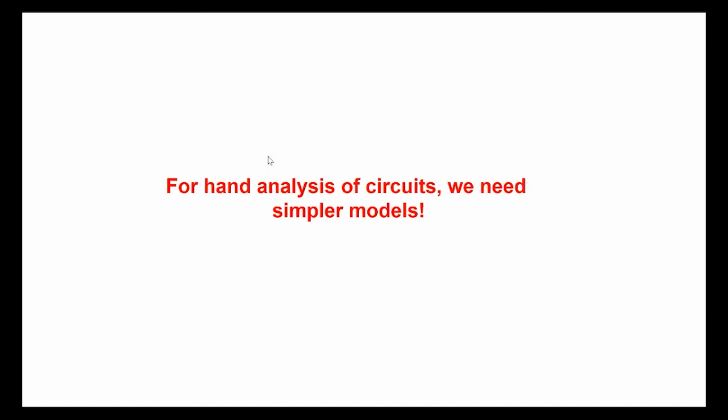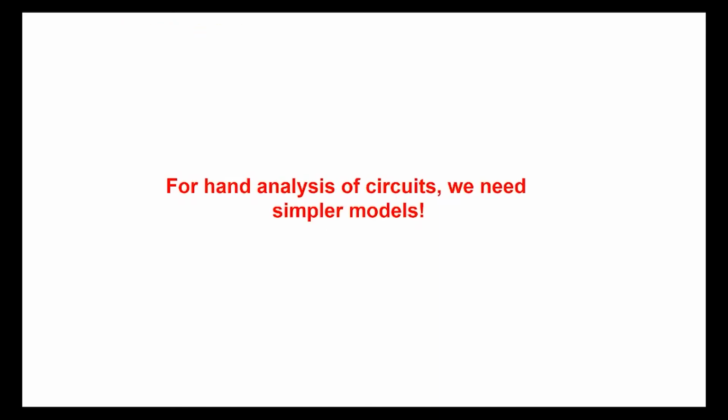All right, but both of these methods that we just saw, iterative methods and the load line method, are complicated techniques and will take a lot of time to solve. And also we said that if you have more than one diode, things become really messy. So for hand analysis, for quick analysis of circuits, we need simpler models. And simpler models basically mean that we need linear models, because linear circuits are easy to solve here.